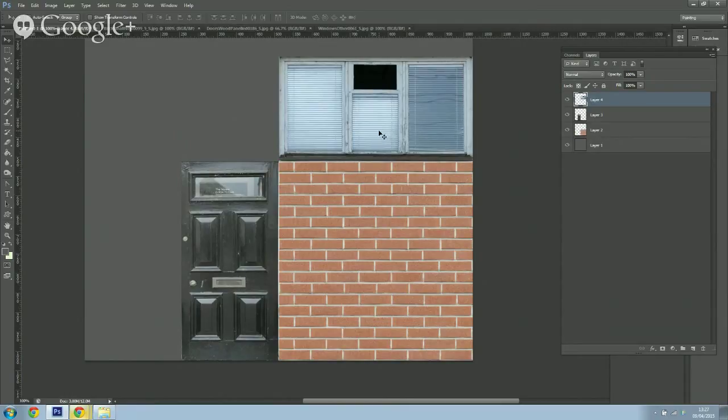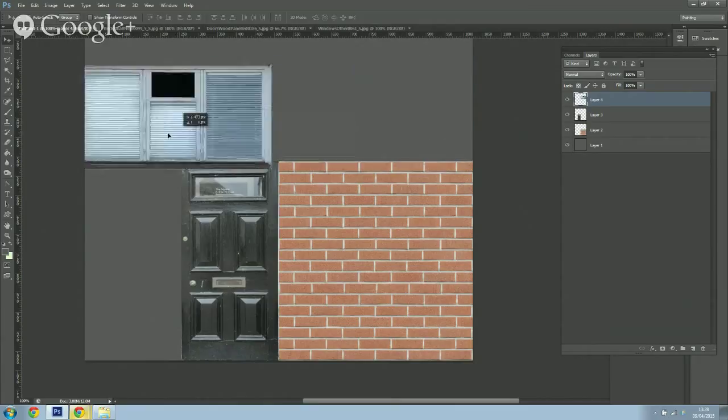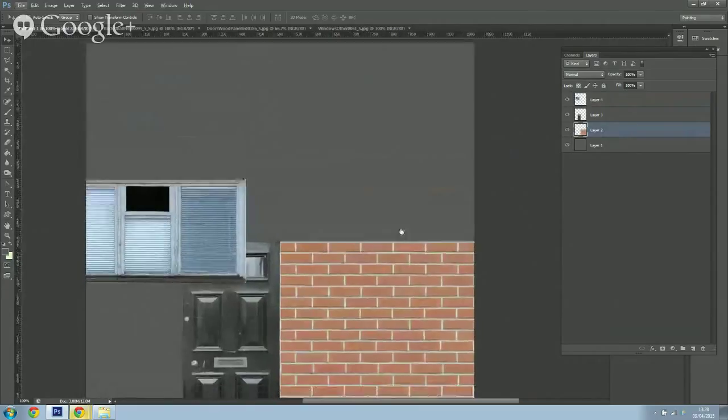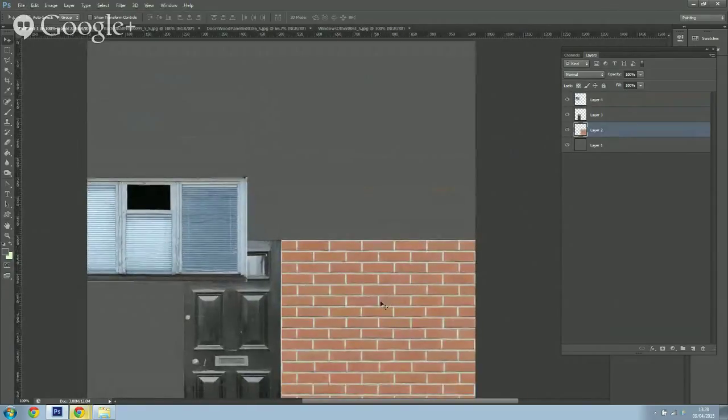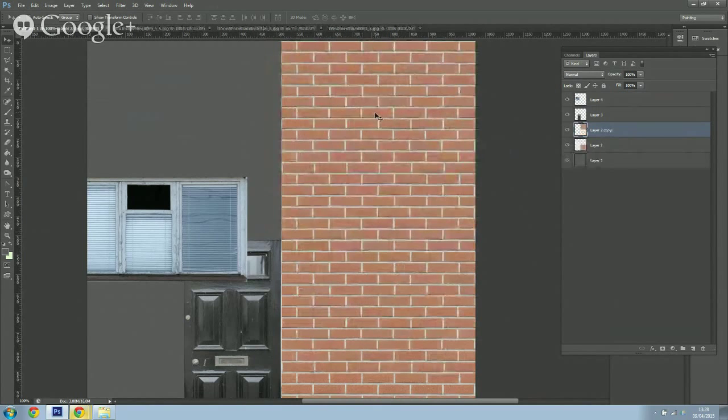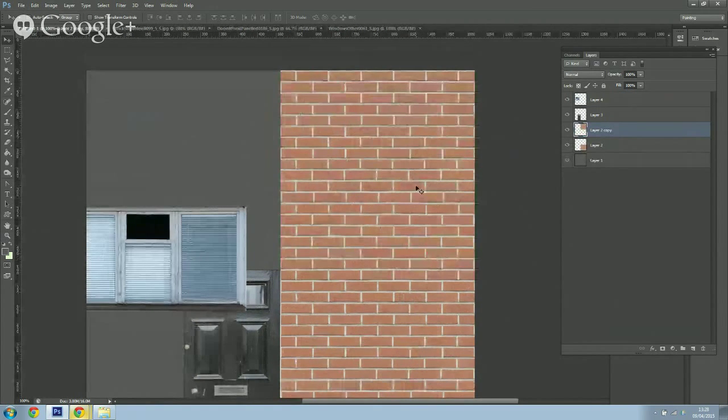Okay, so with knowing that and having that as something that we understand as human beings, that things have to be built within, what I'm going to do is to shift this over to one side. I'm going to grab my actual wall that I've created earlier. And then I'm going to hold down Alt whilst I move the wall up. Okay, so I can see that I'm hovering over the top of it. I'm not pressing anything so far. If I hold down Alt now, you can see my icon changes to a black and a white triangle, one on top of the other. That means I'm going to make a copy. And then I can click and drag and make an absolute duplicate of that wall and place it in the top half of my texture atlas.